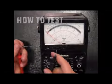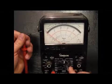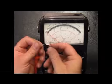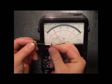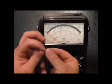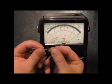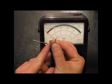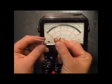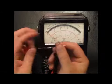Here's a quick illustration of how you can test a diode with an analog meter. I've got it on R times 1, and if we read this way, you see it doesn't read. If you read this way, it reads. So as you can see, this line is on the negative lead, positive lead, it can flow through that way, but not this way.